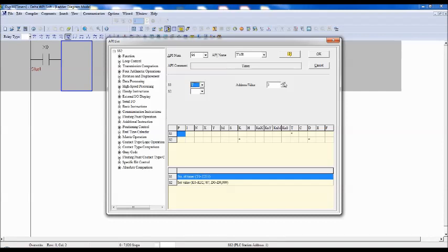In a single program there could be 10 timers, 20 timers. If you keep the same timer name, then there will be an issue, right? So to define the timer name, say for example T1, even T0 is also possible. I will take T1 and then S2, that is this K variable. Variable K is a constant. Here you have to define the time. For example, here it is in milliseconds. For 5 seconds I will take 50. It is not exactly proportional, but for our discussion we are taking 50. 50 means 5 seconds here, assume that. Then click on OK.